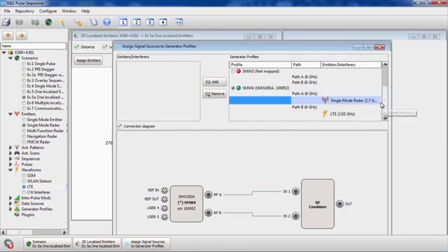You can now generate the signals in each path and combine them with an RF combiner, or if they are close enough in frequency offset, you can also use the stream mapper, add both signals digitally and output them at the RF port of the signal generator.